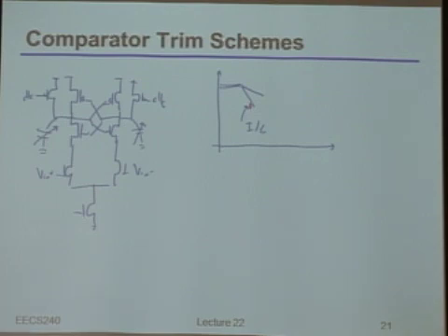So, indeed, this works. But again, unfortunately, it is maybe not the most efficient way of doing things. So, by the way, since we haven't mentioned it before, the way you might actually build one of these variable capacitors, in the simplest example, would be something like this. You'd basically take an array of these unit elements, which would maybe be scaled relative to each other.